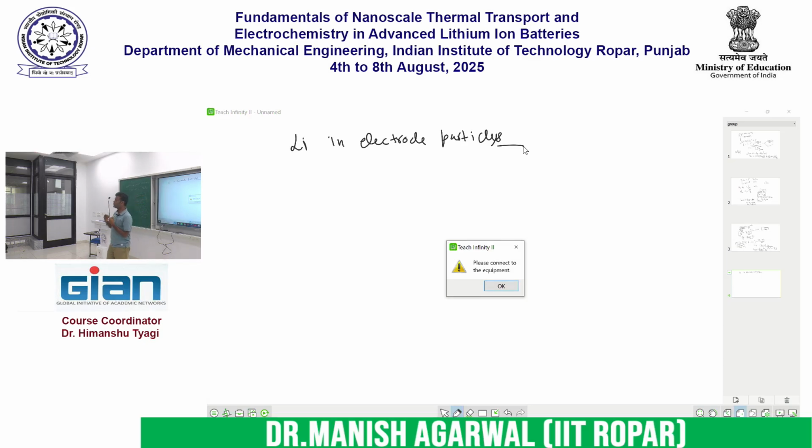But I am losing some detail. If someone wants to know how the temperature is actually varying in these interfaces at the K1, K2 boundary, I cannot tell. I have lost this kind of detail, that is no longer available with me. So if there is some phenomenon happening at this length scale, and if I carry out the homogenization, you cannot expect me to find the answer for that particular phenomenon. That is not possible, right?